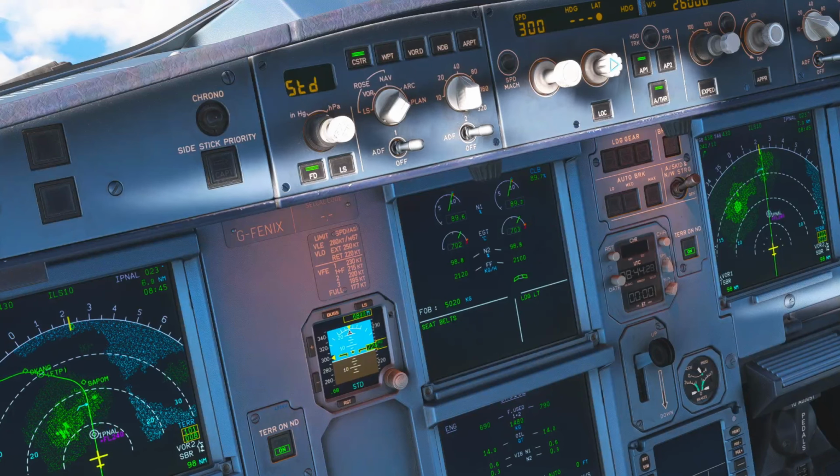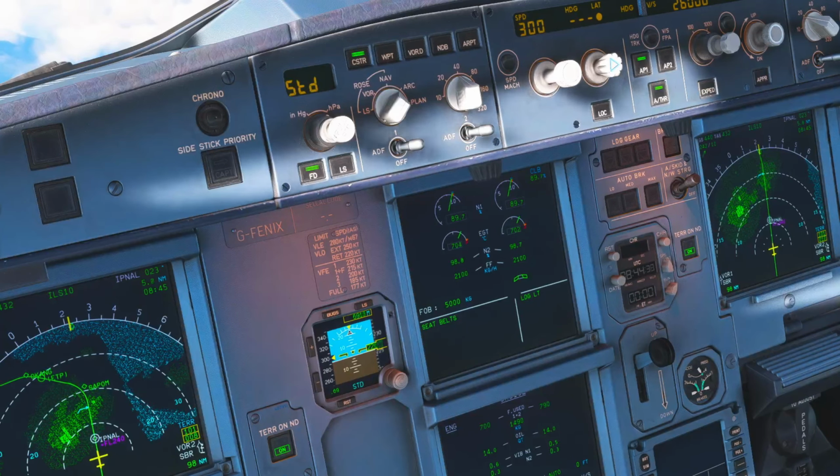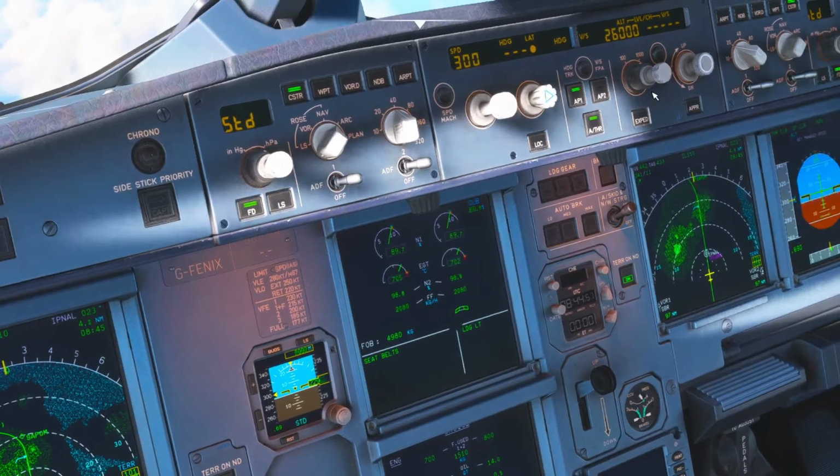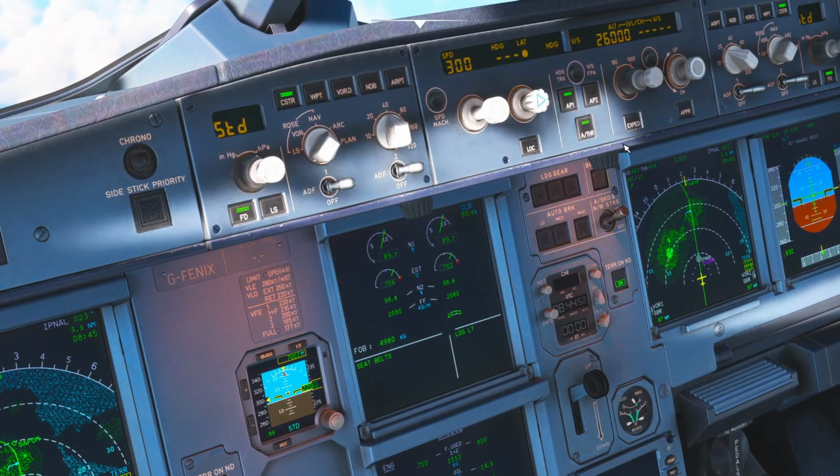To follow the vertical route, or VNAV, when we have a route programmed, we can tell the autopilot to fly the vertical profile of the route for us as well. To climb to cruise altitude or descend from cruise with NAV engaged, rotate the altitude knob, set the target altitude, and push the altitude knob to engage the climb or descent mode.